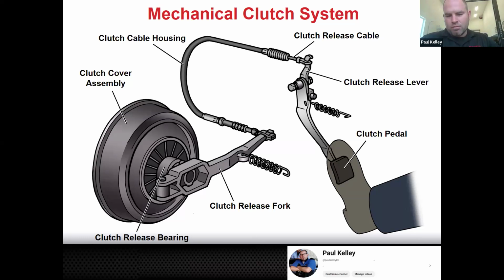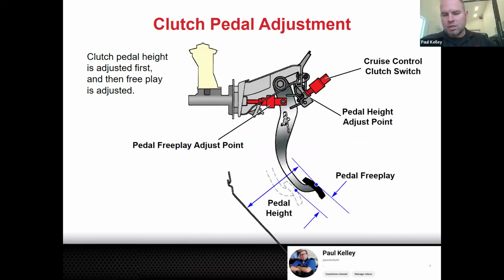Because if you go in there for a clutch concern, it's going to need a kit. If you just do the disc and then you get a noise 6 months later from a release bearing, the customer's gonna have a fit. And partially that would be sort of your fault. It's not your fault because you didn't make the release bearing go bad, but you knew better. I'm telling you that you need to know better. If you pull a transmission to do something, you do the kit. And then you're gonna have a lot fewer comebacks. You do the kit as a minimum, and if you find other damage, then you address the damage.